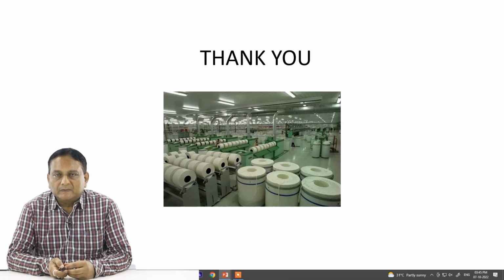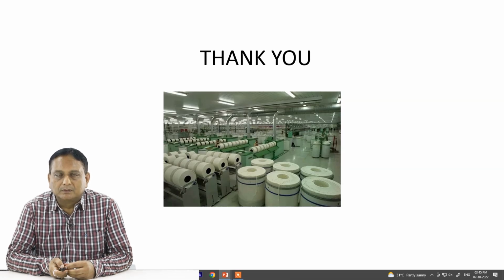So in this particular lesson we have seen how cotton is converted, that is, we get the ring spun yarn through a series of operations, starting from the blowroom, then comes the carding operations, then the drawing operations, then simplex or roving, and finally the ring spinning operations. So these are the different steps involved.